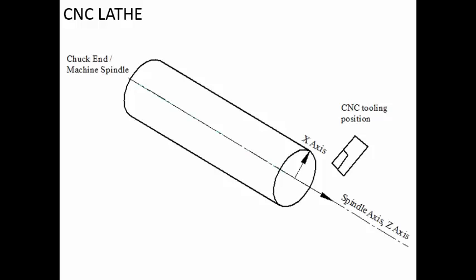But you have certain advanced machines where more axis motions are possible for the tool, and there you may have to individually specify the different motions. So for most of the common CNC lathes, you require only two axis motions. By controlling the movement of the tool along the two axes, it is possible to generate the required profile of the workpiece.